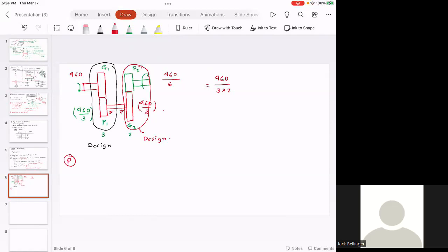A motor shaft is rotating at a speed of 1500 RPM. Power transmitted is 15 kilowatts, and the speed reduction ratio is 3:1. The teeth have a 14.5 degree pressure angle with 25 teeth on the pinion.